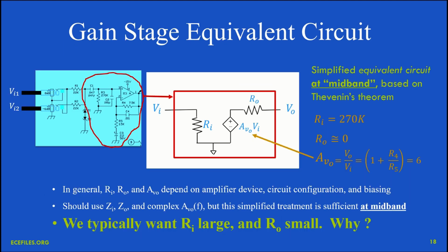So we can take everything we've just said and use it together with Thevenin's theorem and come up with a replacement for all the circuitry, including what's inside here, with just 3 components. Let's look at the output of this first. This is what's called a controlled voltage source. The value of it depends on what the input is. So it's a number times Vn.